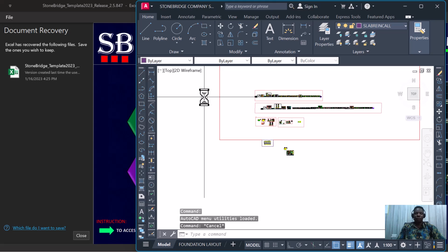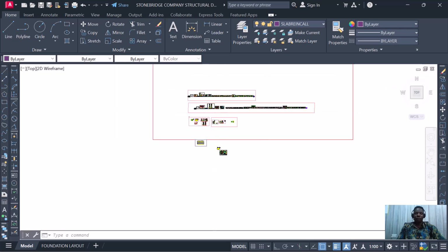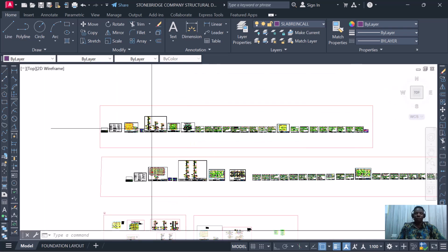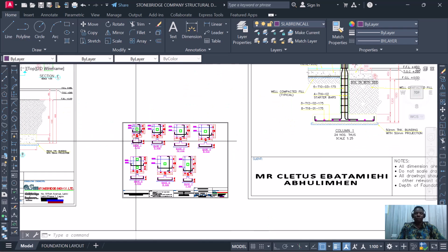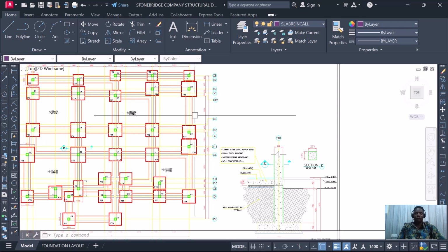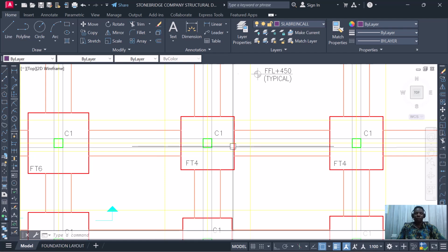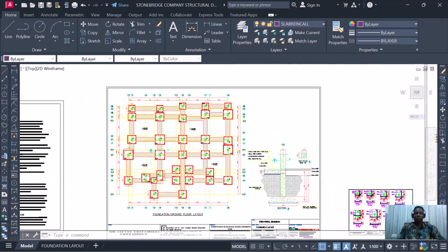What we need to do is just use the template. But there's an advantage here. Once you open that particular detailed template, every other drawing you copy from the one you've already exported from Prota Structure, once you copy it and paste it over here, it's going to give us a different view. So now you can see we'll have a different template that already exists here. You can see different drawings that already exist with a pad footing.